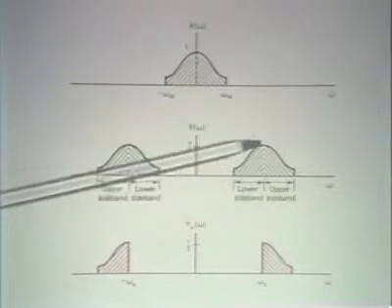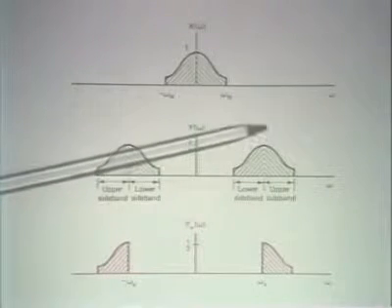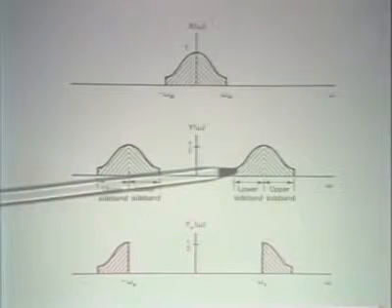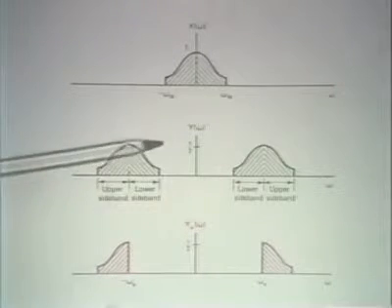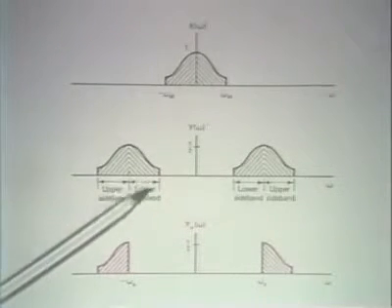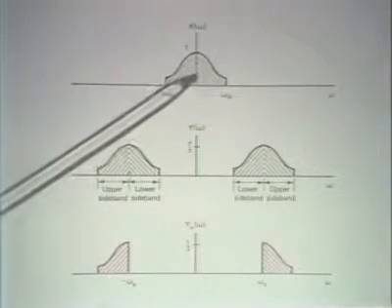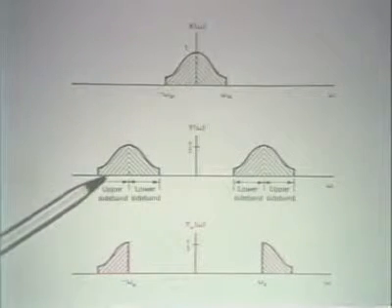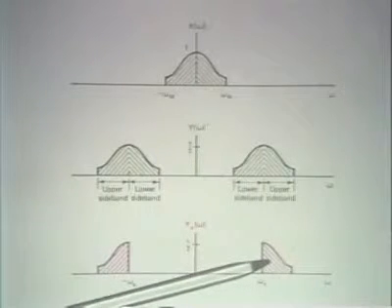And we could imagine building a real valued signal by eliminating what I refer to here as the lower sideband out of the positive frequencies and the lower sideband out of the negative frequencies. In effect, we've taken just the positive frequencies here, shifted them there, the negative frequencies here, and shifted them here, and the resulting spectrum is what I indicate below.